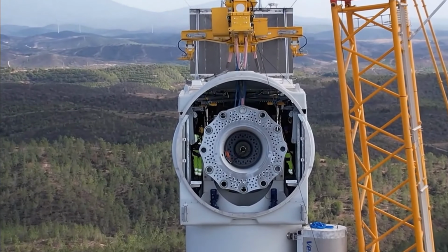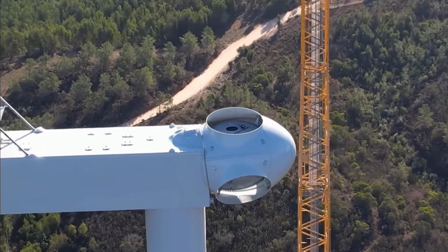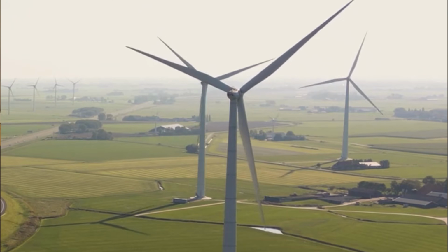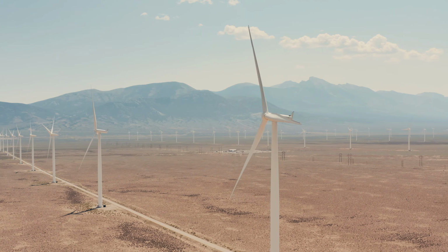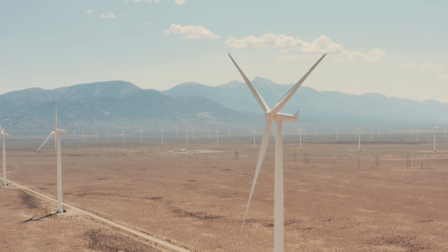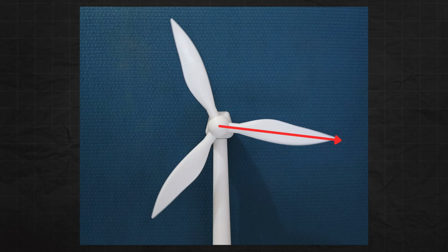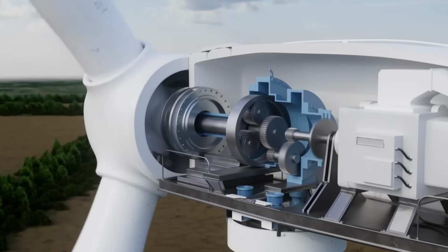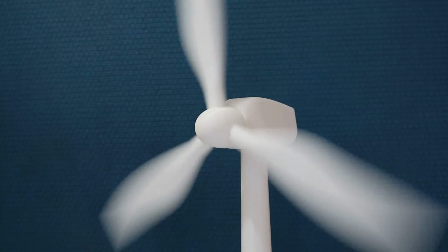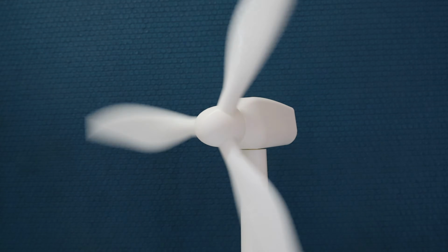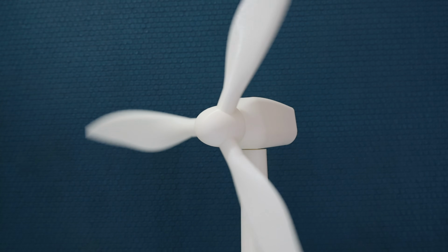This leads to the power output of these turbines to be relatively inconsistent if compared to the 3-blade design. Hence, an odd number of blades is preferred for balance, because as one blade is horizontal, its 2 resistances are balanced by the 2 other blades. Thus, the 3-blade design contributes the least stress on components and rotor vibrations. Turbines with odd number of blades are also the most consistent in poor wind conditions.